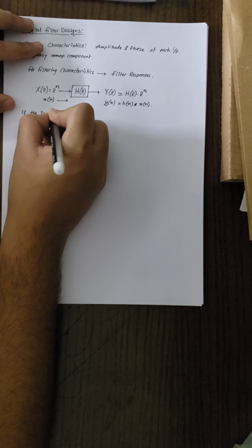Then y of n can be written as the amplitude of h of e to the j omega times cosine of omega n plus theta plus angle of h of e to the j omega. So we will try and prove that y of n will be equal to this expression, which is dependent on the frequency response of the transfer function, both in the magnitude and the phase aspect,